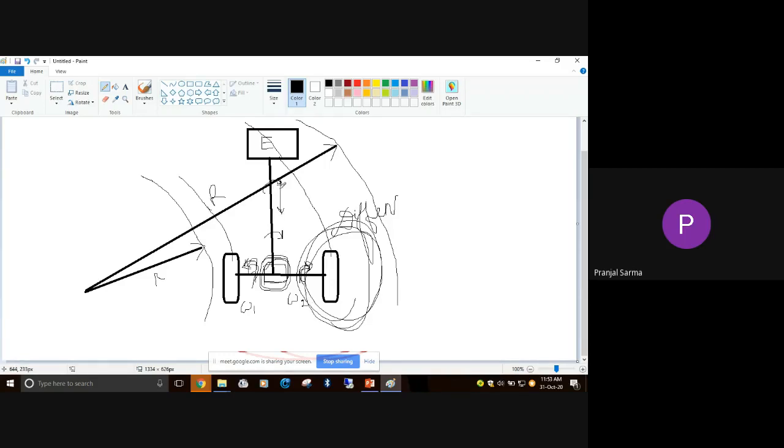One thing is that from this side the propeller shaft is having a rotation, with angular velocity omega. From here we can give the motion to this side and that side, and we use the differential, which has all those bevel gear arrangements. The next thing is that we can differentiate the velocity of the two wheels also, which is required, because whenever we take a turn, the vehicle has a finite width, a finite distance between the wheels.